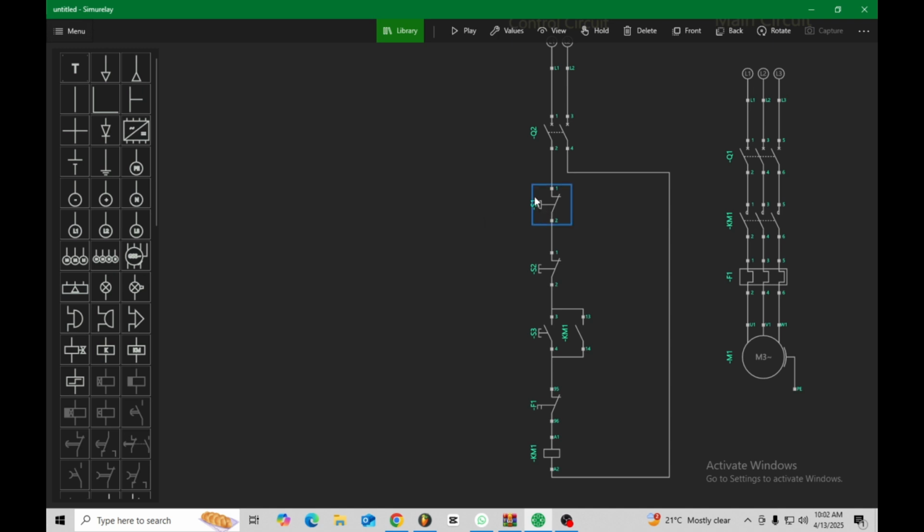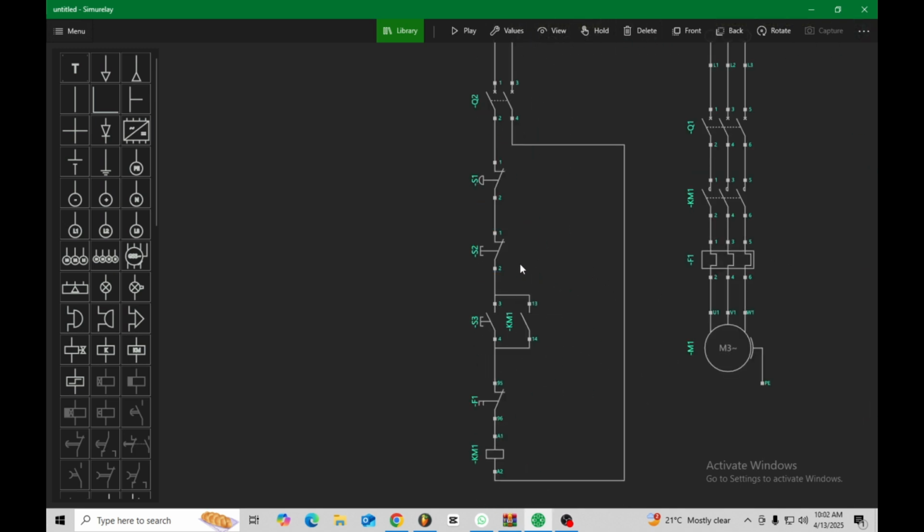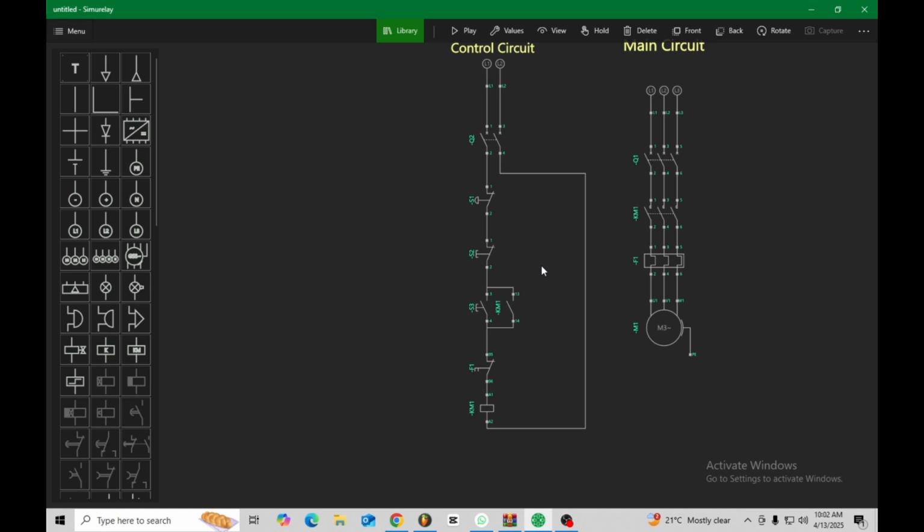Okay, cool. After the emergency stop, we have a stop here. So if you want to de-energize your coil, you need a stop button. Without your latching system over here, you're going to have a push-button setup, which you would normally see in cranes or something like that, where you want the motor to move just a little bit to the left and the right. You would use it like this without the latching system.